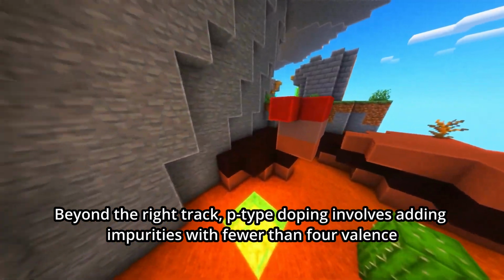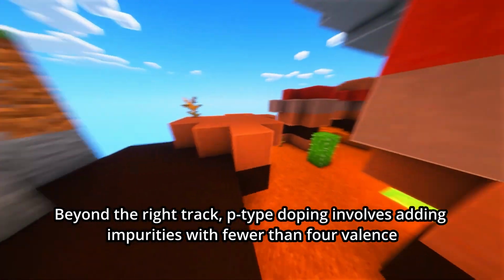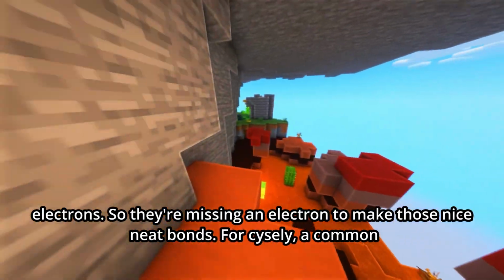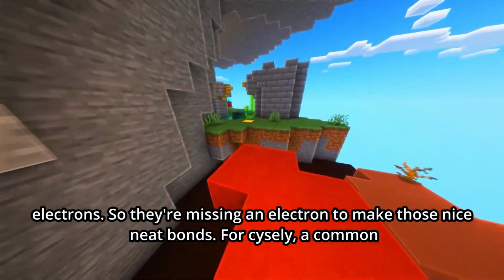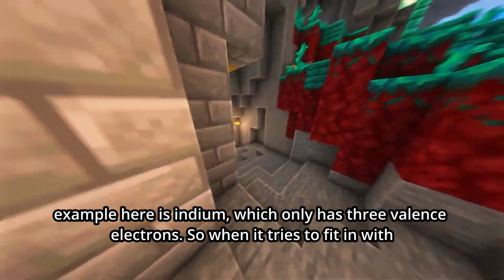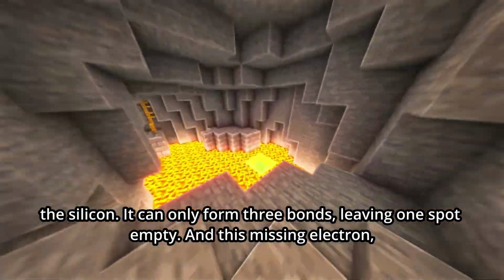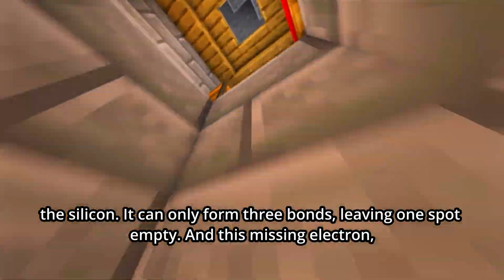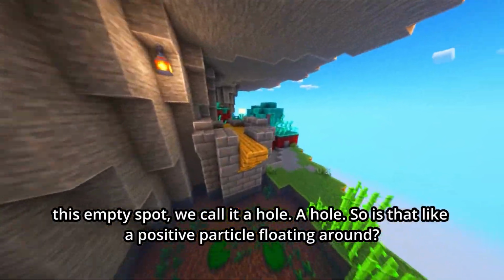You're on the right track. P-type doping involves adding impurities with fewer than 4 valence electrons. So they're missing an electron to make those nice, neat bonds. Precisely. A common example here is indium, which only has 3 valence electrons. So when it tries to fit in with the silicon, it can only form 3 bonds, leaving 1 spot empty. And this missing electron, this empty spot, we call it a hole. A hole.